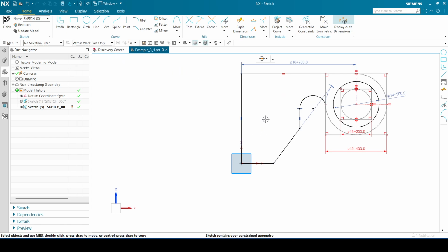So now we have some conflicting dimensions, so let's quickly see. Here it has an equal length constraint to this one, and these ones, I think our issue is with all the 90-degree angles that we have for our square with this horizontal, it's complaining.